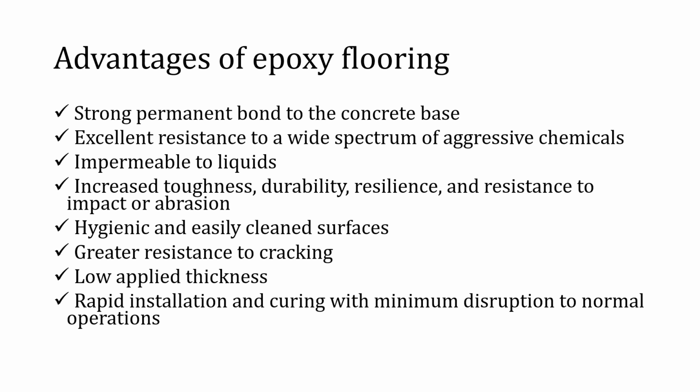Epoxy flooring has several advantages and benefits compared to other floor coatings such as vinyl or polyurethanes. The benefits include aesthetic features and lower maintenance requirements, higher safety due to its non-slip profile, durability, abrasion and chemical resistance, and environmental stability. The main advantages of synthetic resin flooring can be summarized as a strong permanent bond to the concrete base,